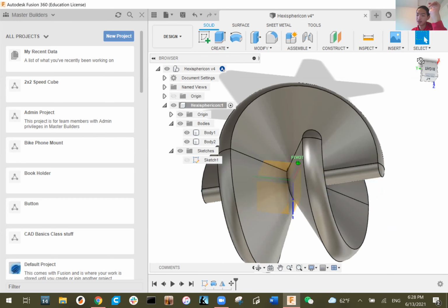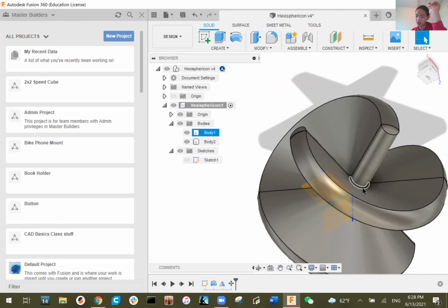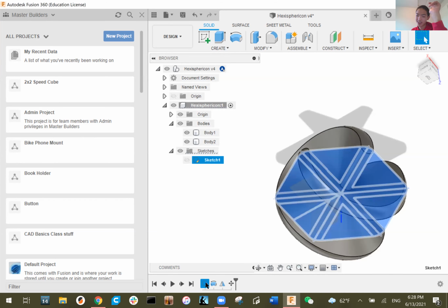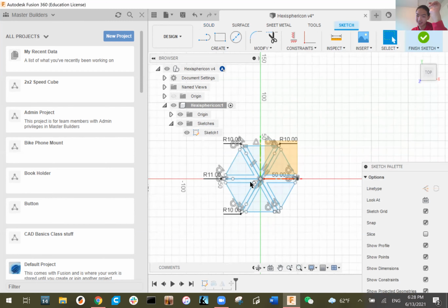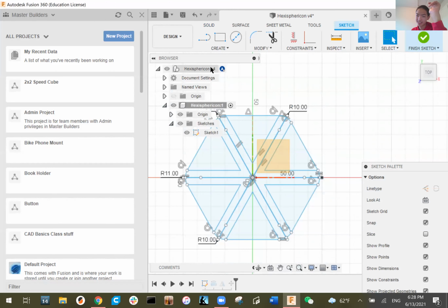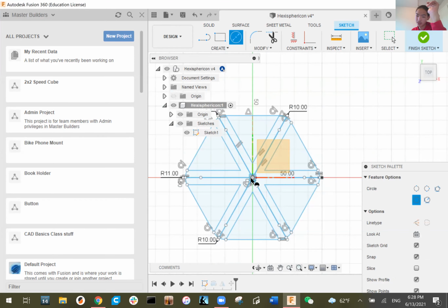And then the next thing we can do is we're going to go back into sketch. It's a bit repetitive, the steps, but we're just going to go back into sketch. And now we're going to draw a huge circle at the center of the sketch. So we're just going to go back to design history in the first sketch, and we're going to draw a huge circle. The circle just needs to be, we're going to put it at like 60 millimeters in diameter.